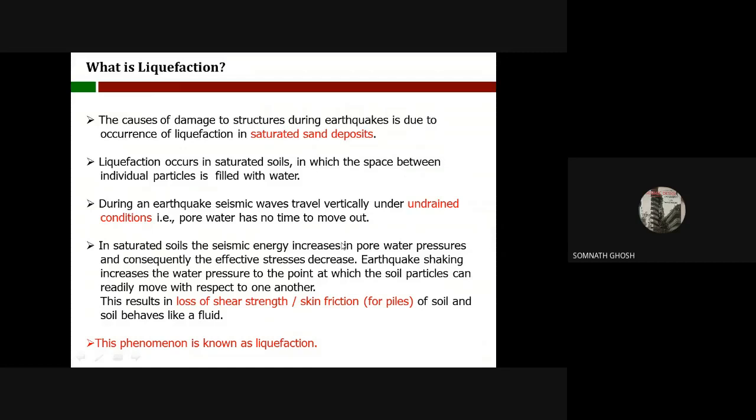Sand dominates, right? If the clay is more, then there is no problem. But if there is a combination of sand and silt, yes, definitely you have to be very careful about liquefaction, right? That is why saturated sand deposit, not only sand deposit, means sandy soil.